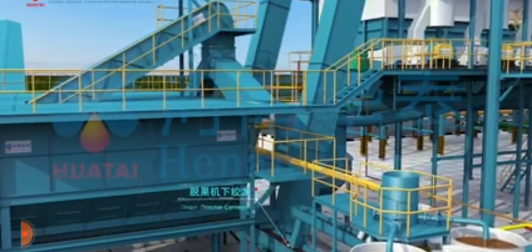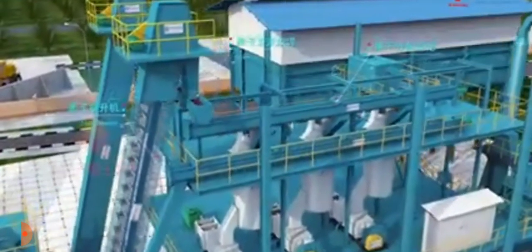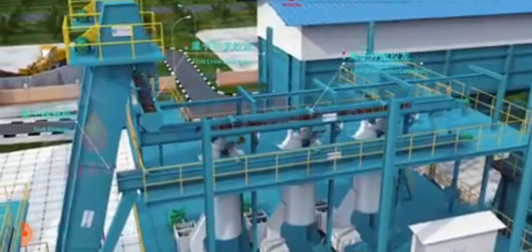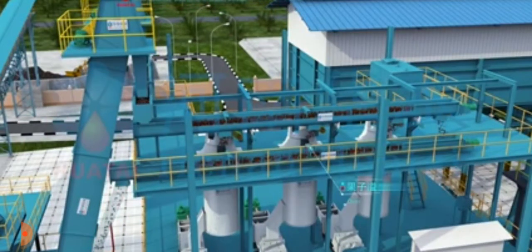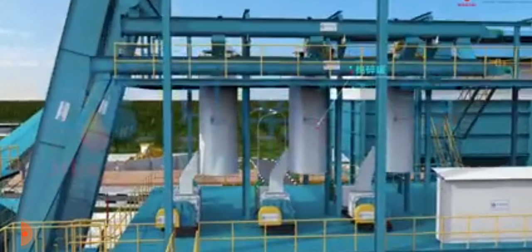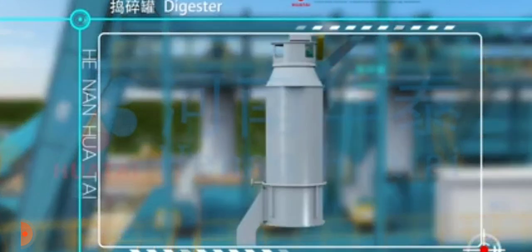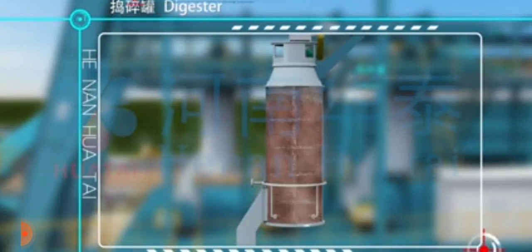Fruits are conveyed to the fruit elevator from the screw conveyor under the thresher, and elevated to the fruit cross conveyor. They are transferred to the fruit distribution conveyor. Redundant fruits are recycled by the overflow fruit conveyor. Fruits enter every digester, where they are heated and digested.